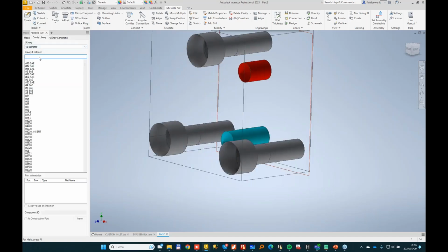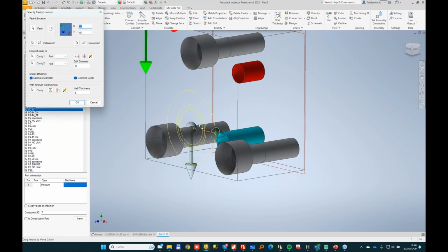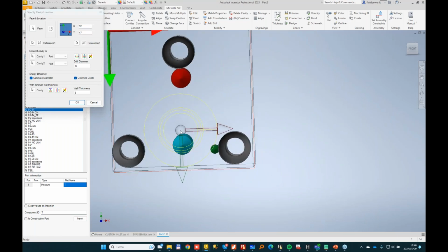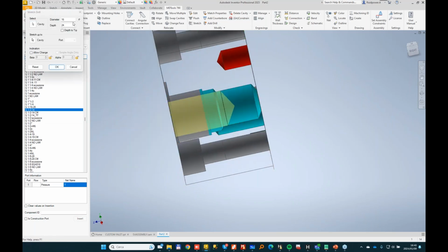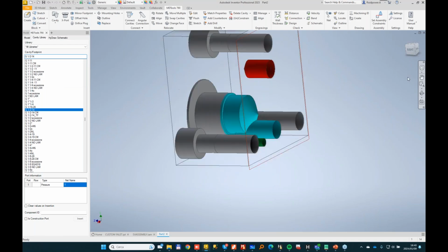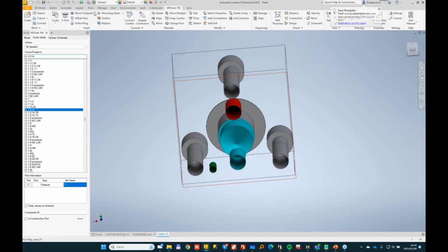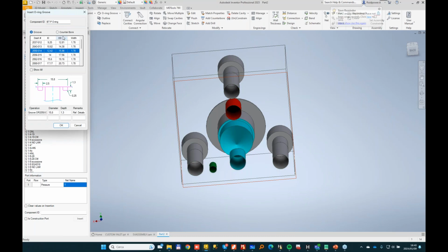The tank port was a G1/2. That's our tank port, and we position it somewhere here. And we can reduce the drill depth. That's okay. We can add O-rings. So now I do manually the O-ring groove for this drill. This was, let's see, counterbore 0.13. And similarly, maybe it's a groove.